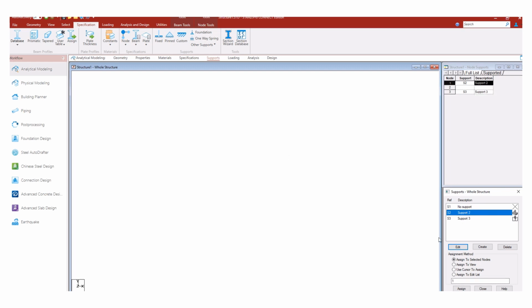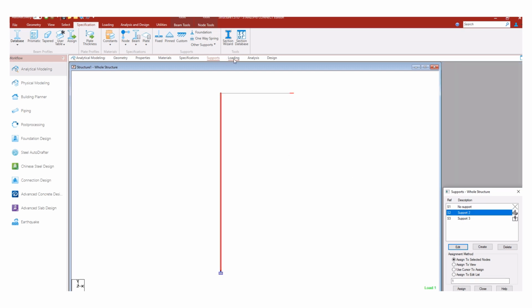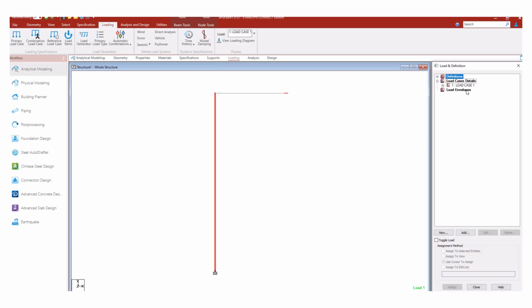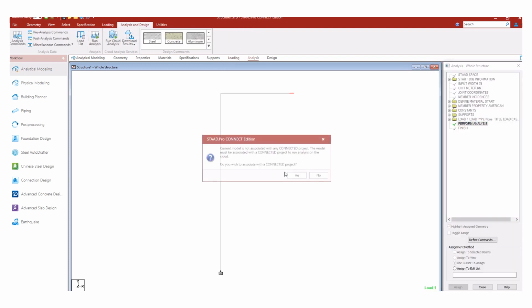So next, this is the fixed support, and if you go to the loading, we have applied a concentrated load at the middle. When it is applied here, it will try to deflect vertically only. This joint also will move vertically. This joint cannot move horizontally, so it will rotate. Okay, so we will see the bending moment diagram for this one. So we will analyze this, run analysis.